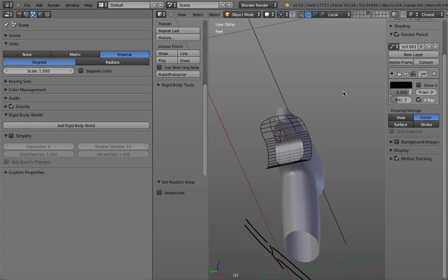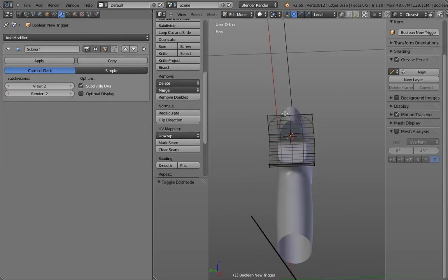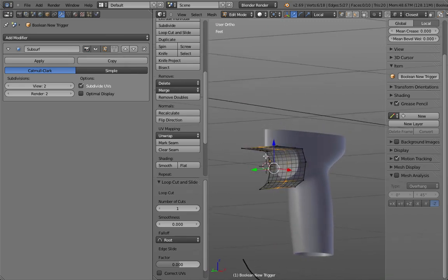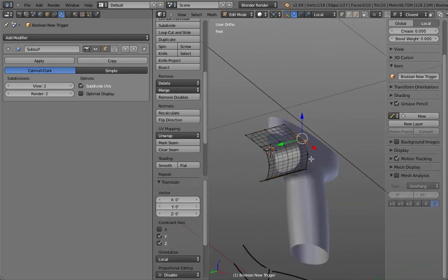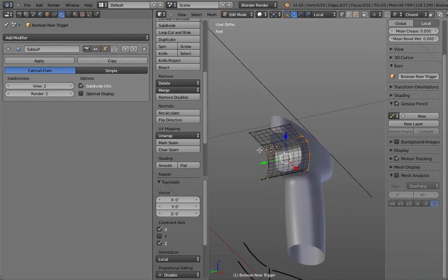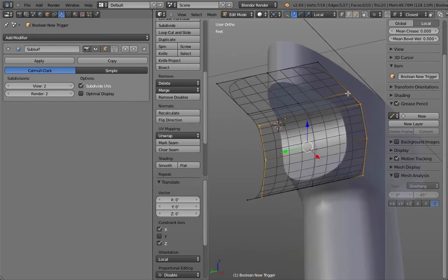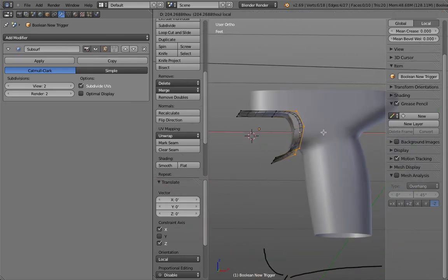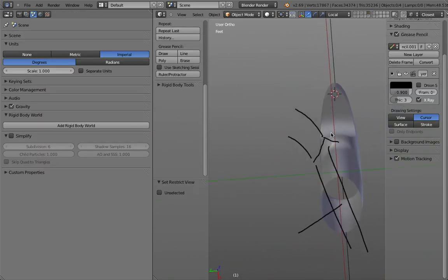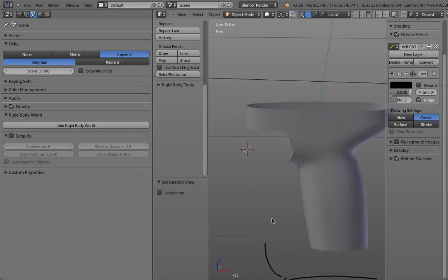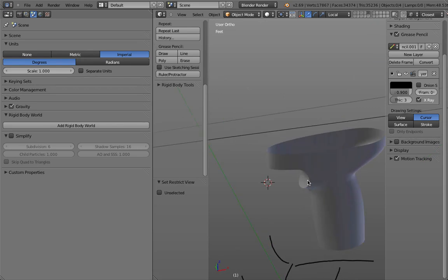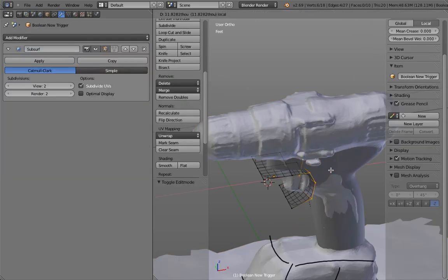Let me show you one nice trick. So it's also about ergonomics and how it feels. So I create a center line, and then maybe those points here, I have to play with this a little bit. Actually, not this one. I move backwards. So you see that this cutout gets a slight curve, because your finger will go around, and maybe you want those transitions to be nice.